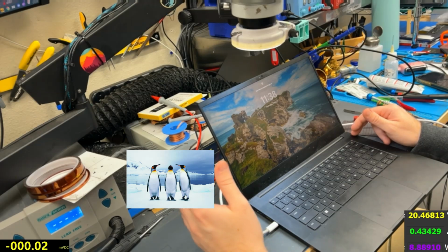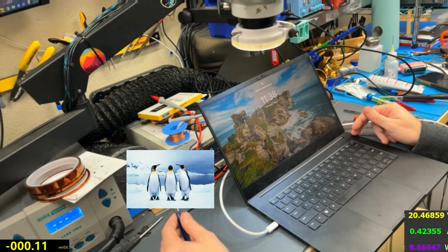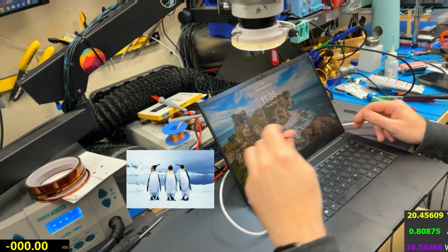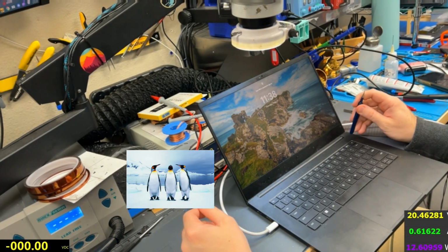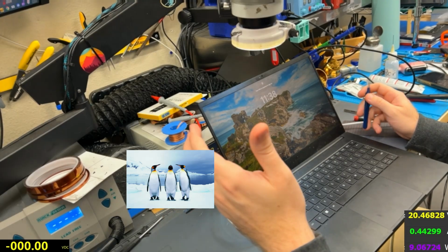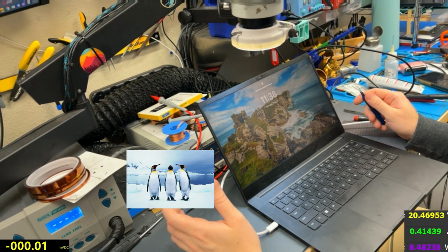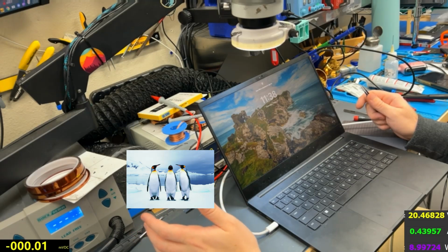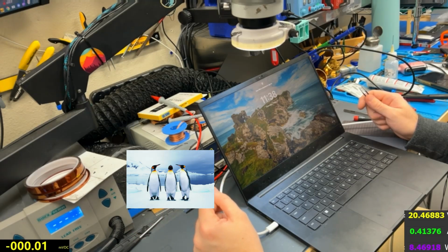Generally what you look for is, you have your short circuit on your 20 volt, you measure it on the CPU inductors, whatever you get. What you want to see is when you remove the shorted MOSFET, that the resistance on that line climbs up in some significant regard. I assume the reason these Ryzen CPUs maybe survive more is the resistance to ground on that line is naturally low. So when the short occurs, the 20 volts generally doesn't go directly into the CPU. It offshoots to ground instead, or something like that. That's probably not close to exact, but in practical thought that kind of makes sense to me.